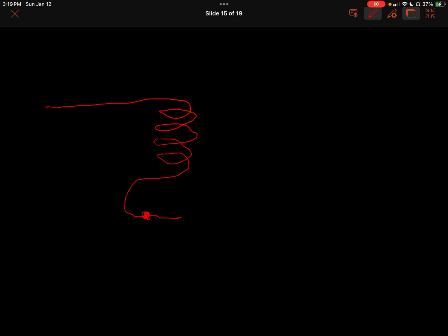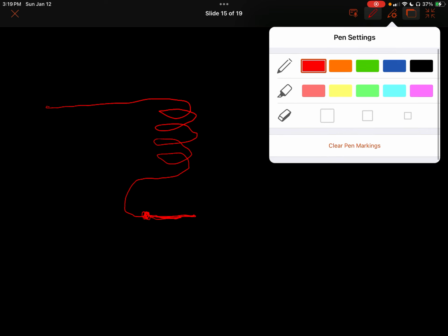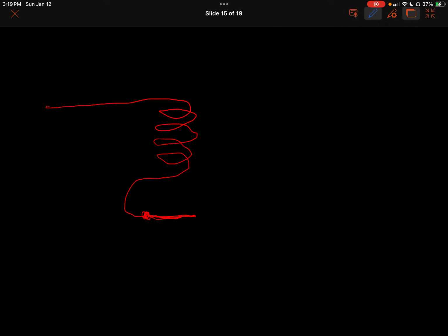And so we have a switch right here, and then there's an output side, the contact here. Under normal operation, power comes in, flows through this coil, and then out through the other side, out to our load.